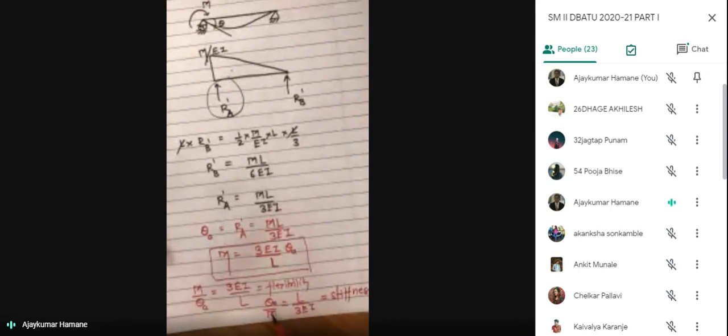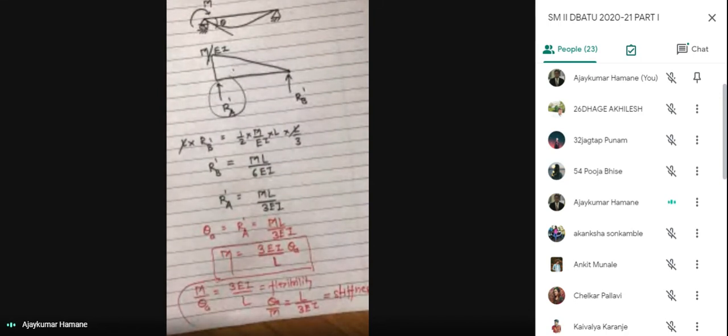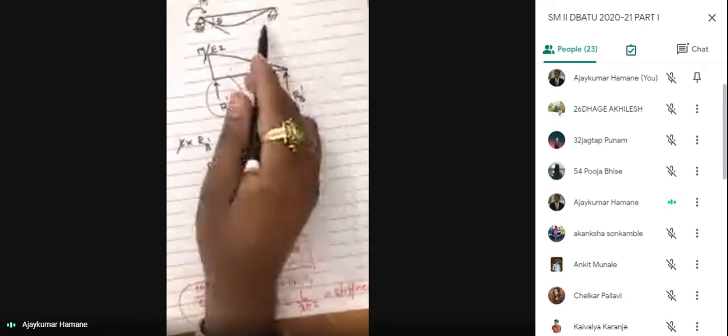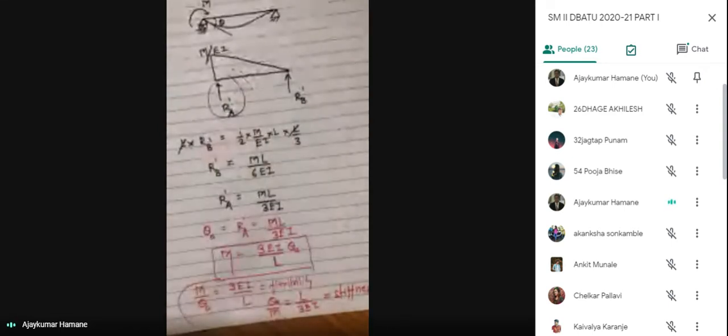That is the rotation required per unit moment, when you apply the unit moment. So what is the displacement? That is the rotation, L upon 3EI. Okay. So here remember, whenever one end is rotating or any force is applied, to get the flexibility and stiffness, the other end should be pinned or hinged. Okay. So that time we have this one.